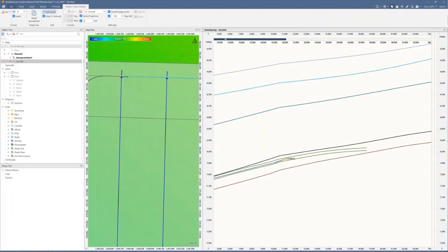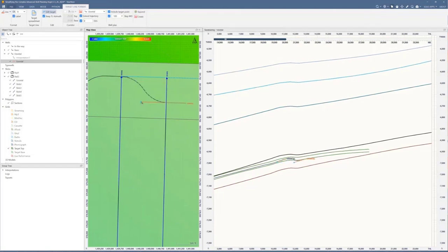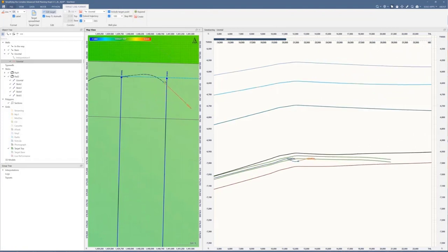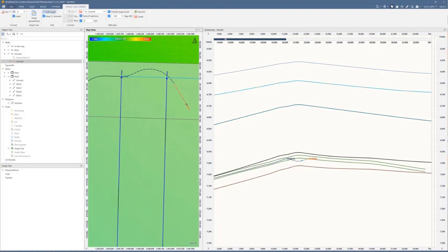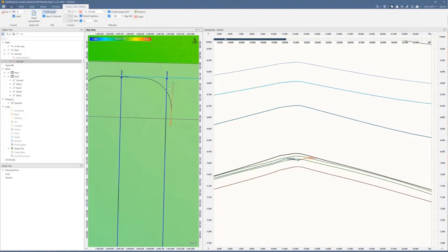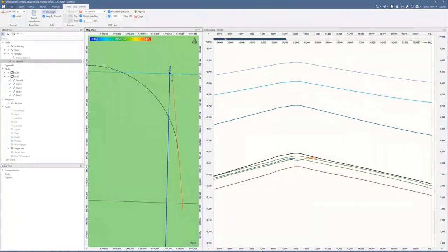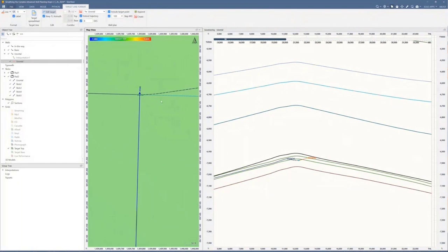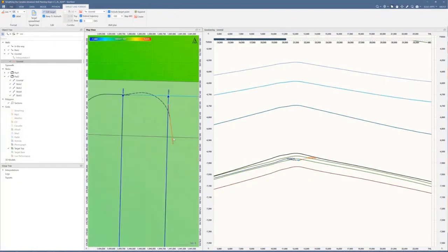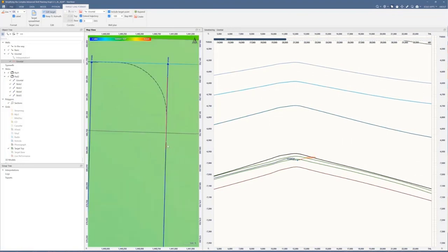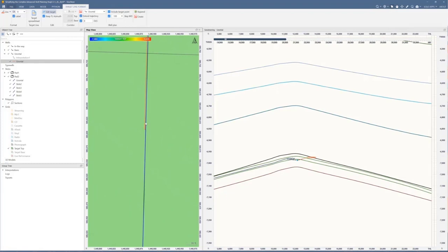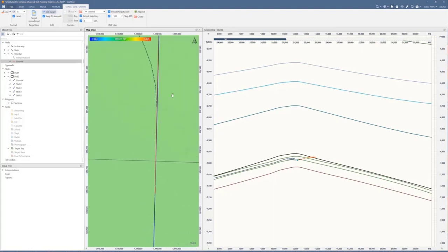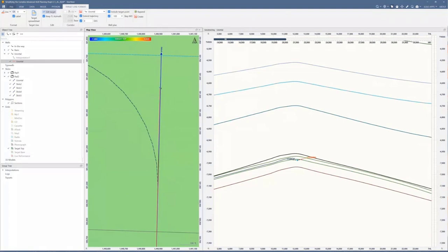Because I'm continuing to do that turn, I'm going to keep it at 8 degrees dogleg severity. And then again, I'm just going to grab that target line here. I'm going to reorient it, and blue's always going to be the start, and green is always going to be the end point. So I'm going to zoom in and bring this in to match up with the well path, and I must have been a little bit over 90 degrees, or maybe not. It looks like it's kind of deviating from that. So I'm just going to grab that and make sure I can reorient this to be pretty much on the stick. And we're using these sticks that we generated as guides. And we'll use this process for a couple other well plans.